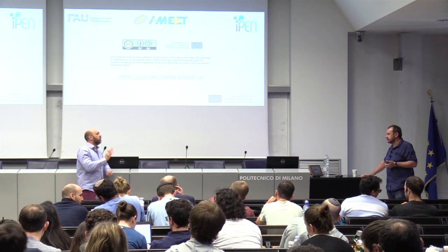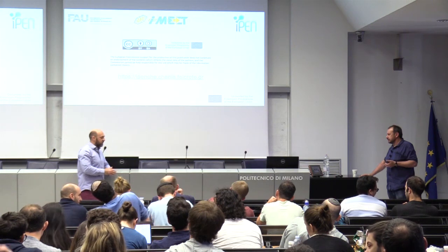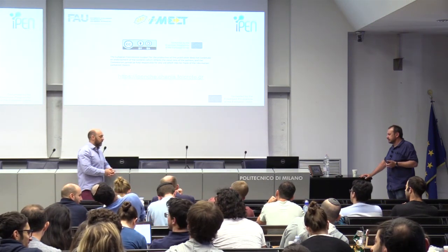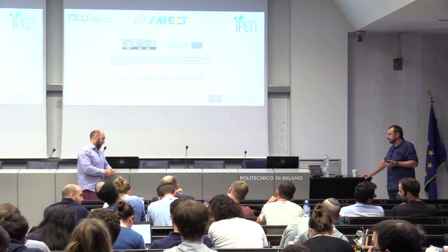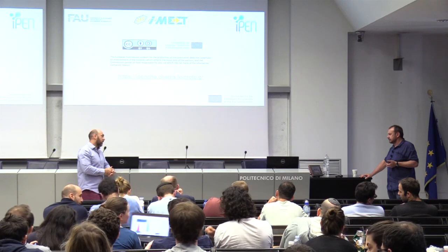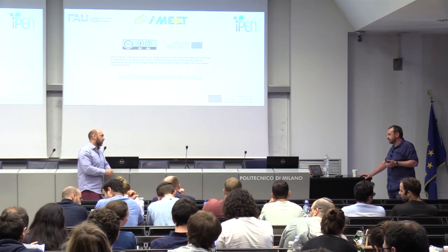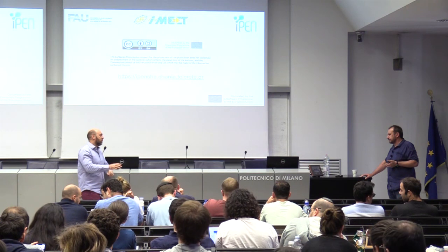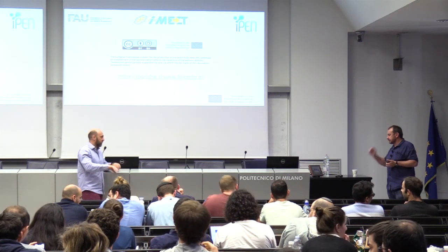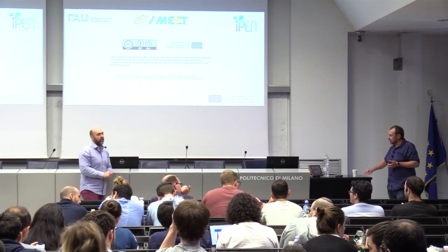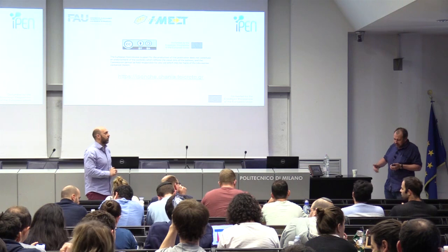And this means that if you are using green, the divergence will be higher, no? Compared to 1064. But you're using femtosecond in order to not induce thermal effects on the sides, no? Yes, generally with femtosecond you get the clean cut.